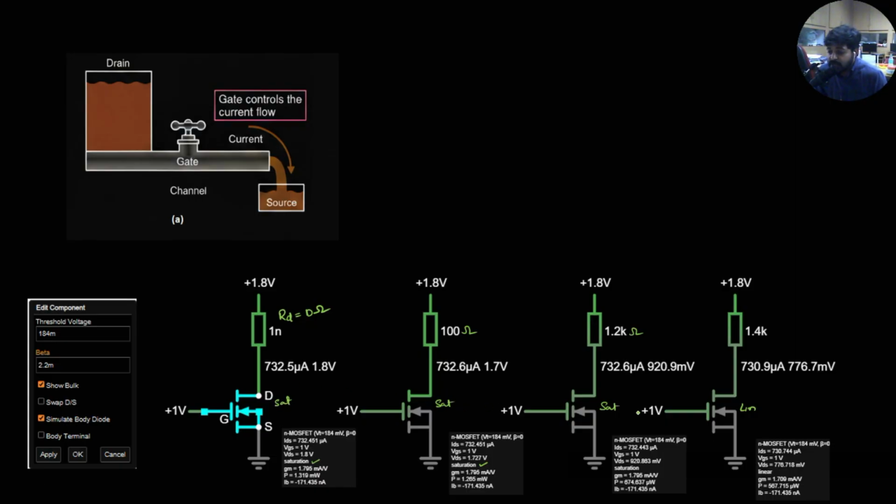So what might be the issue? Why is the transistor going into the linear region? The reason is that in all the cases the control voltage at the gate is the same, and the supply voltage is also the same, I just change the RD values. When the RD value is very high, it limits the current flow.